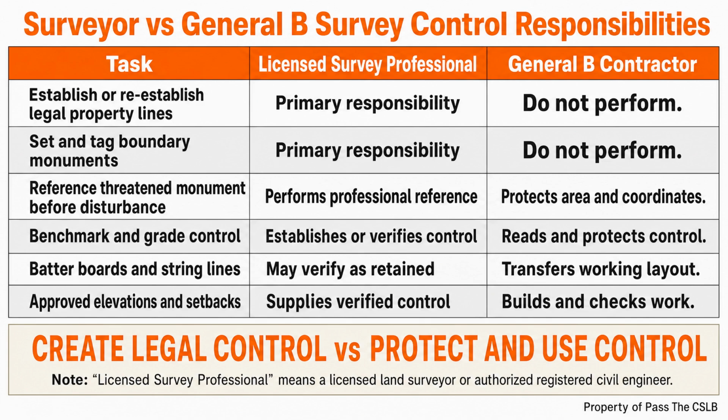Suppose a crew finds an old iron pipe near a corner of the lot. One worker thinks it is scrap. Another thinks it is the property corner. The correct contractor decision is not to choose the more confident worker. The decision is to protect the object, check the plans and survey information, and coordinate with the proper survey professional before disturbing it.